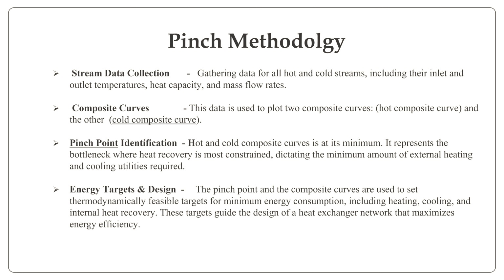In pinch methodology, these are the data showing how the pinch can be achieved. Pinch analysis means the wastage of heat can be recycled through all the processes in process and chemical industries. First of all, the data is to be collected for the hot and cold streams, like inlet and outlet temperature, heat capacity, and mass flow rates. These data should be collected before starting the process.